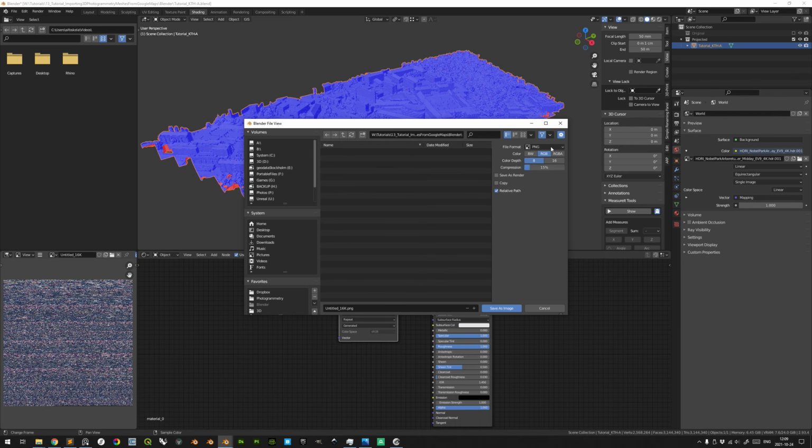And yeah, we're in Blender here. As for the file format, you can choose, of course. PNG has a non-lossy compression format, so it might be adequate for most users. If you choose JPEG, you will get a smaller texture file size than with the PNG. You decide which format you want to save it to. I think for this tutorial's purpose, a JPEG is perfectly fine. I'll just make sure that it's 100% quality. And everything looks good.